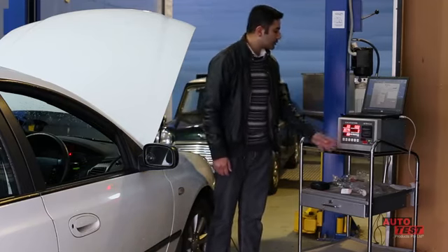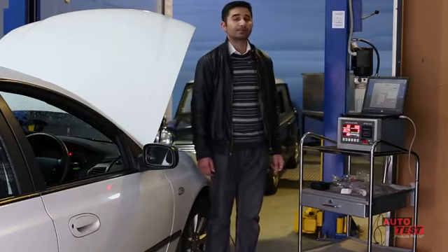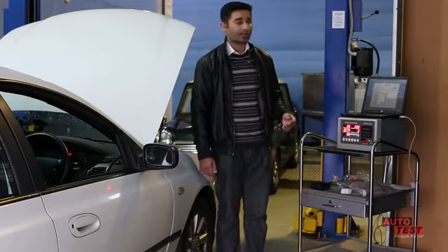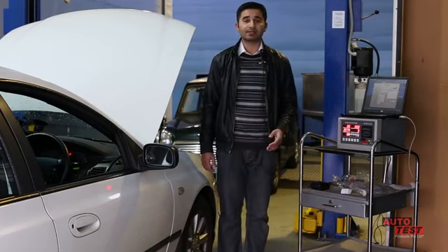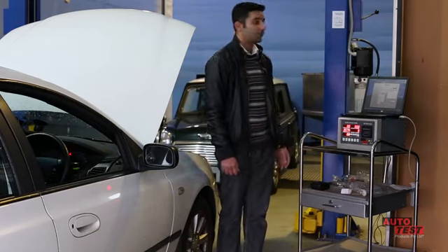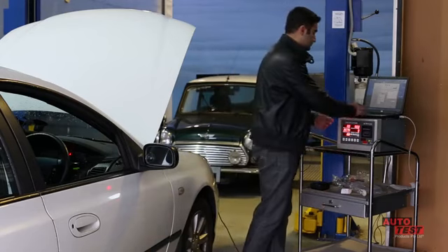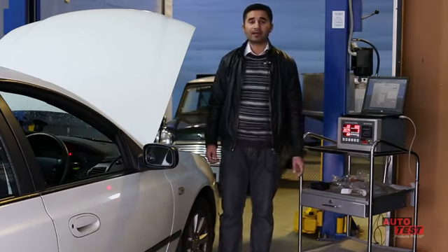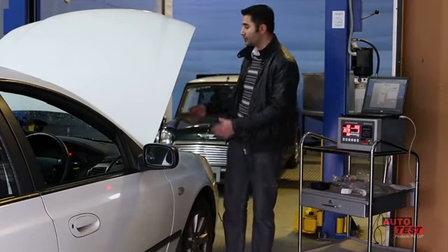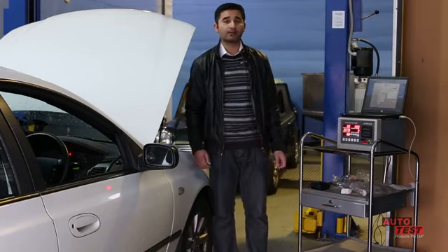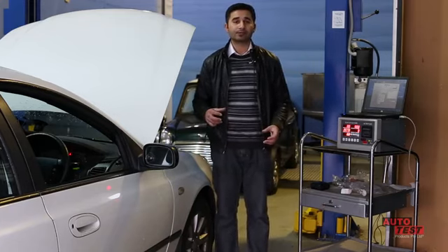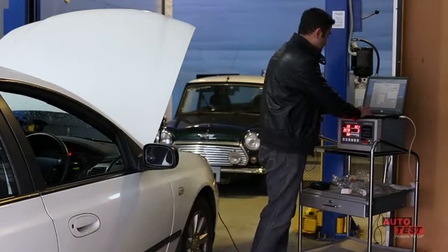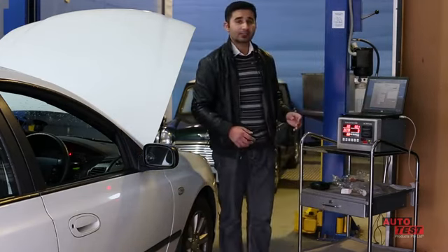But since we're going to use a PC, we'll simply go to the PC screen and type in the vehicle's details, the type of engine it has, and how many cylinders it has, and then we'll continue to begin the test. This software works with a webcam as well. If you have a webcam, you can point it at the registration plate of the vehicle to record that registration plate along with the test report. Okay, I'm going to press continue to begin the test.